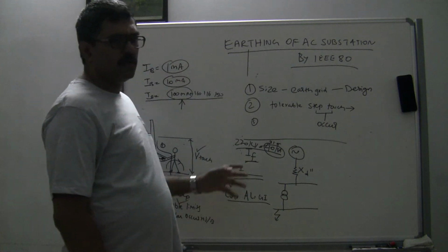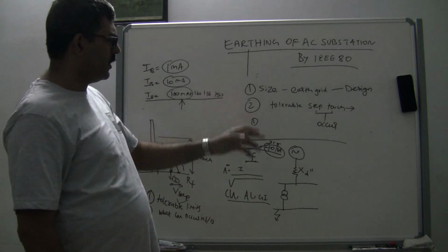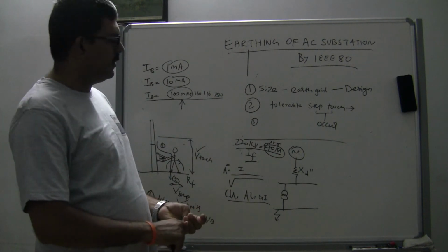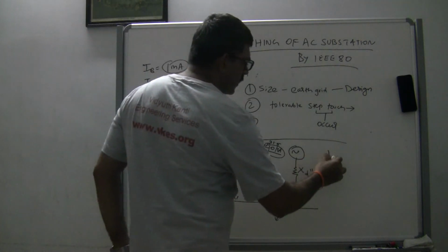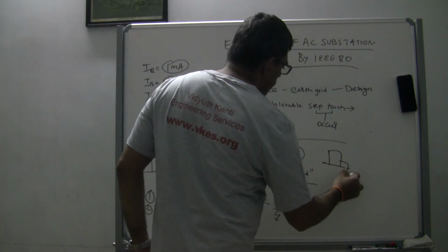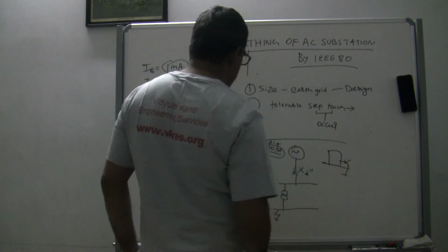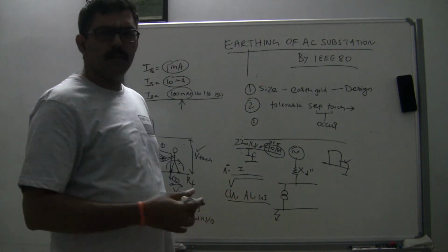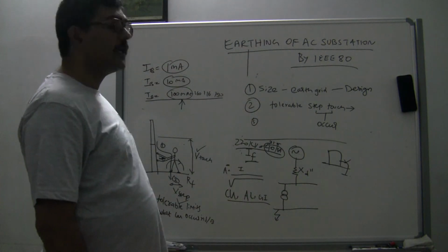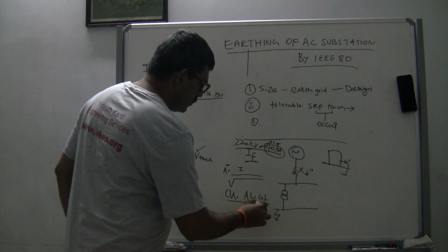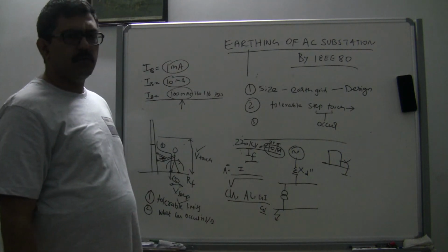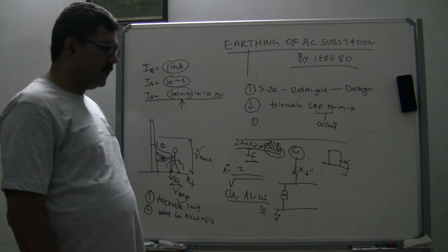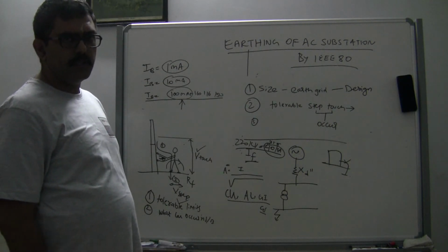The protective conductor for the earth grid, and the link connecting the electrical equipment to the earth grid, can be copper, aluminium, galvanized iron, or galvanized steel. The choice of conductor depends on geography, country, and client, and it changes.